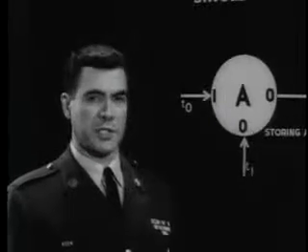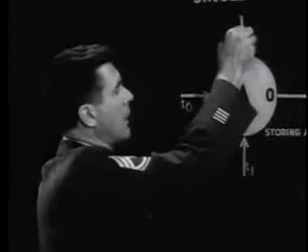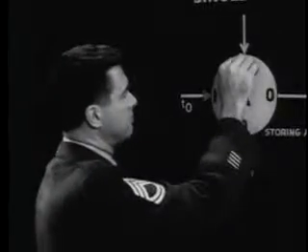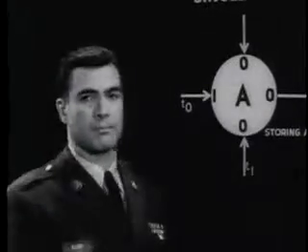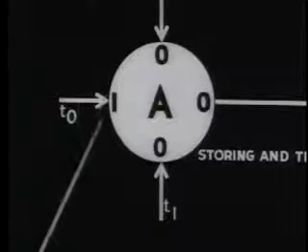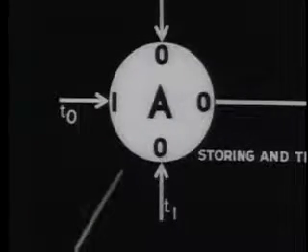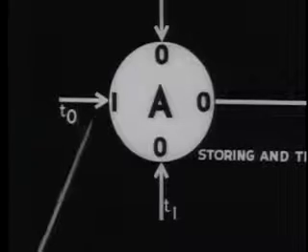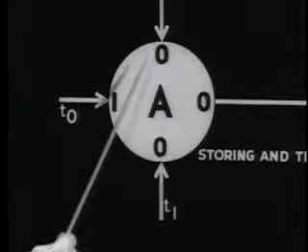Suppose, for example, there were several inputs coming into the first core of a loop. In this way, there are 3 inputs here. The one at the left will set the core to binary 1. The top and bottom inputs will clear it back to 0.